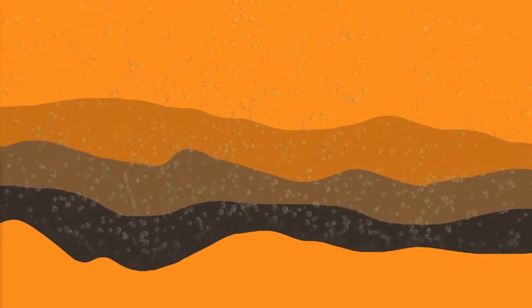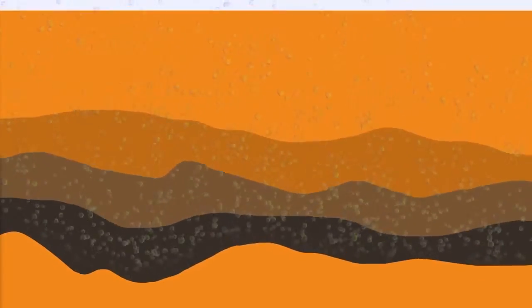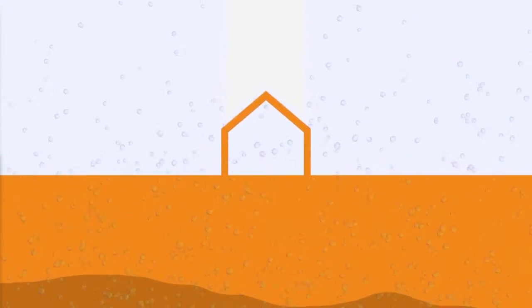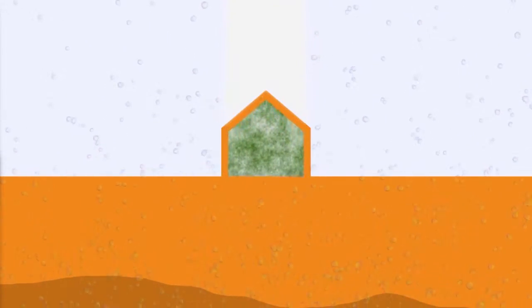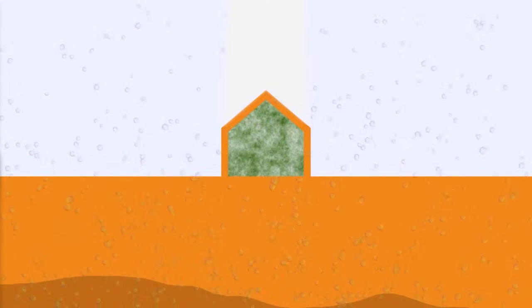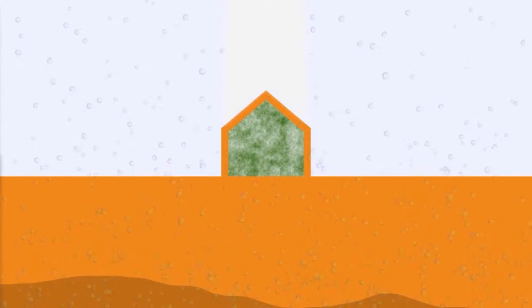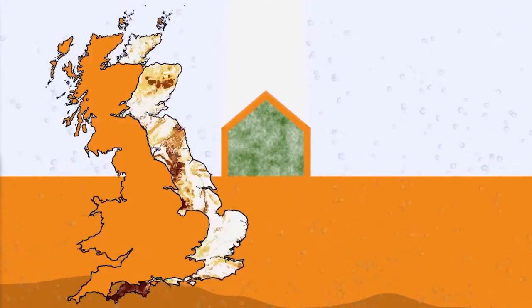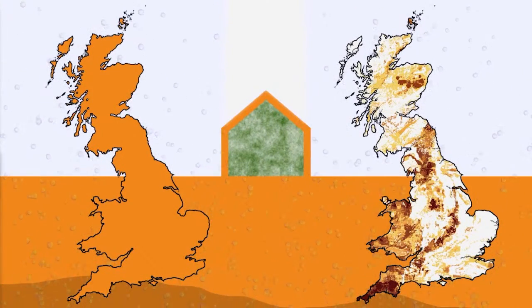The trigger level for dangerous radon exposure is 200 becquerels, and this can be reached where ground-produced radon gas concentrates in enclosed spaces. For comparison, the background level of radon activity is around 8 Bq. Radon levels will change across the country as it depends on the geology of the area, i.e., where granite is prevalent as the underlying rock. Radon maps are produced to indicate where the underlying geology is likely to produce a significant amount of radon and require protection to be provided to any development.